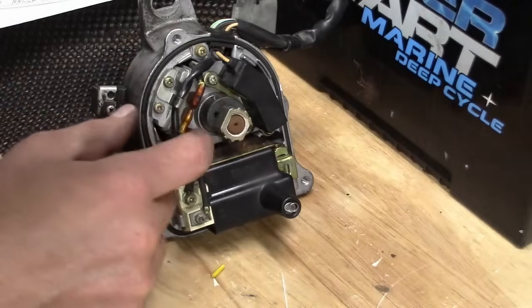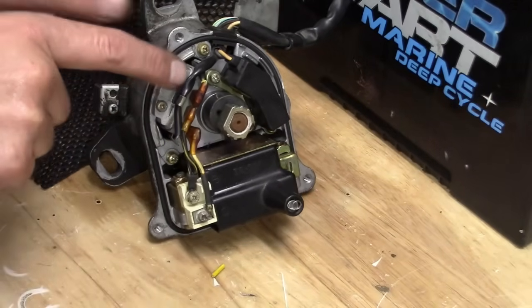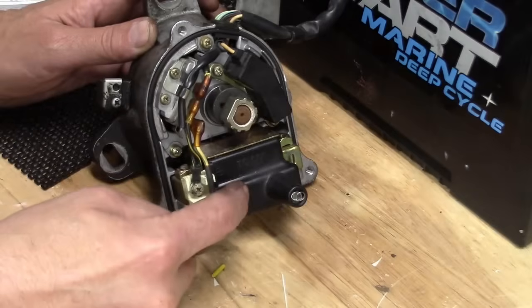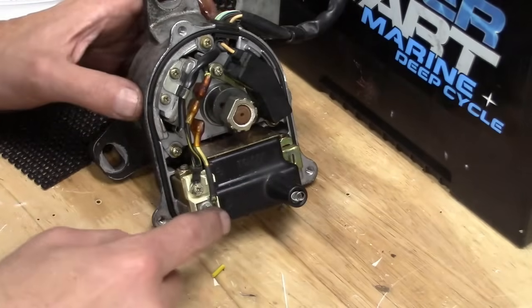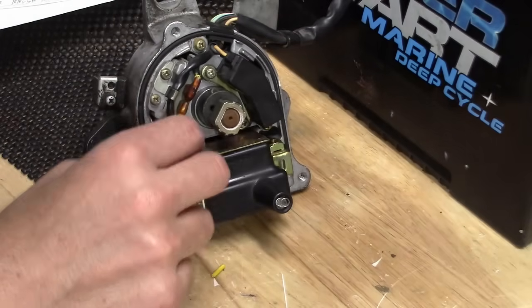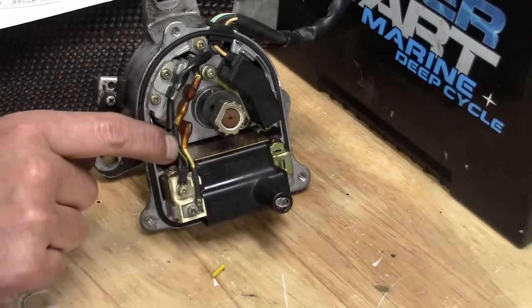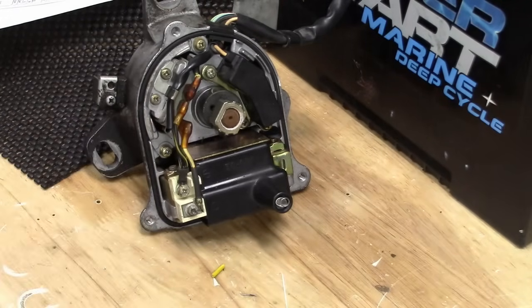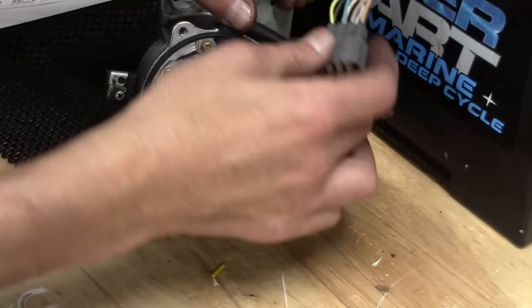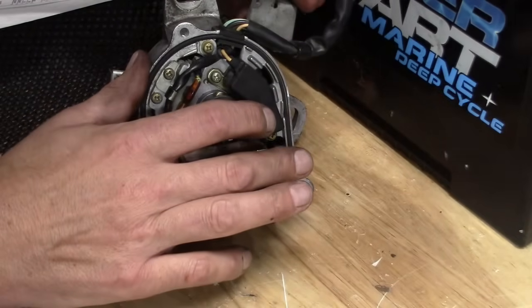Right here, we've got a whole bunch of wire plugins. That is going to be the ICM right there. And this obviously is the ignition coil. And look at that, they even give you a positive and negative as well. Check it out. On the positive, I can see a black wire with a yellow stripe. That is this wire up here on the connector that I initially measured power at.